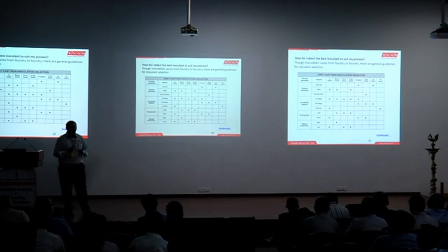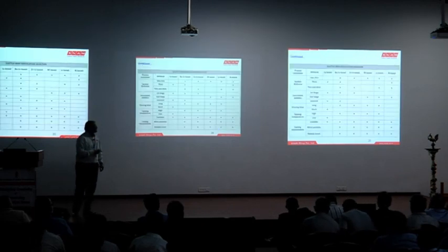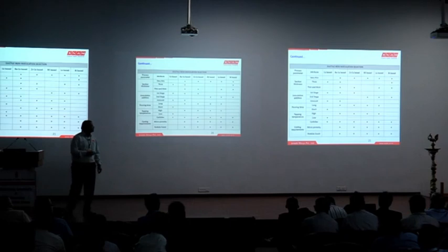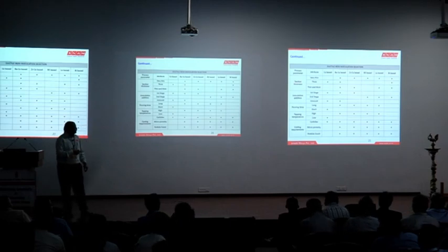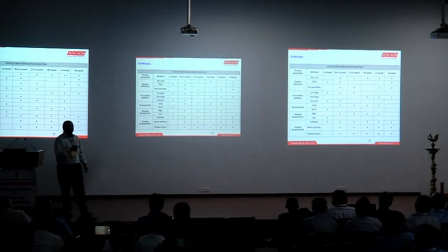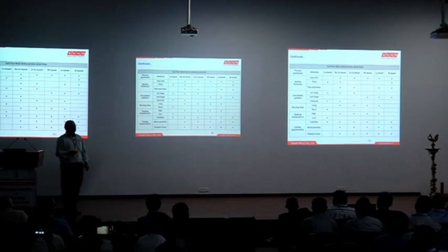I'm putting a clause beneath. This is again a ductile inoculation selection. So with respect to varying levels, your pouring time, tapping temperature, and the method of inoculation, you can select different inoculating elements and inoculant types.